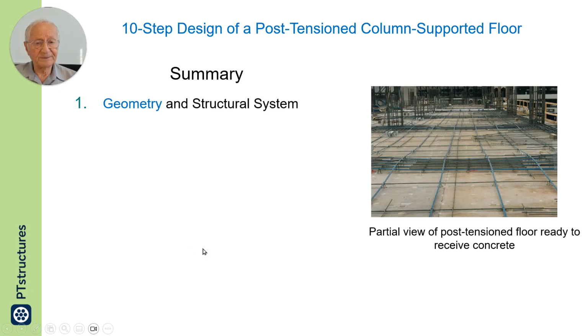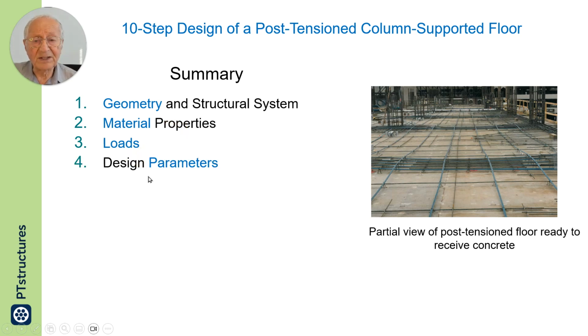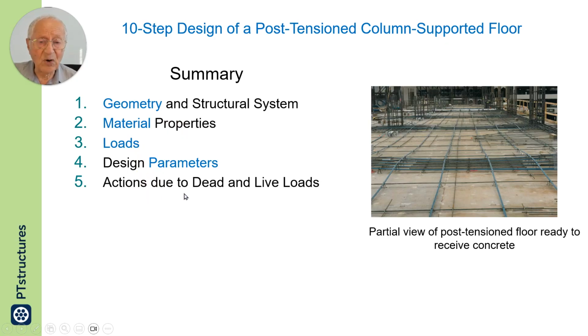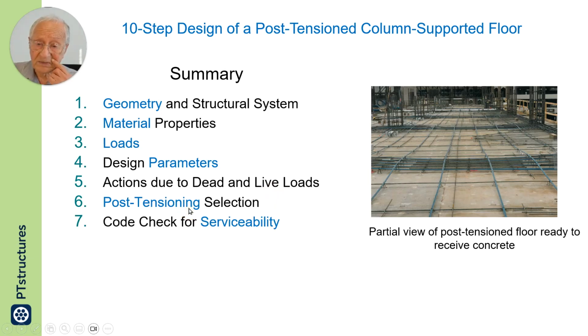So in summary, I defined the geometry, that was step number 1, defined material properties, defined loads, defined design parameters, then calculated the moments due to dead and live loads. We selected post-tensioning using two assumptions, pre-compression and uplift, to enable us to come up with the initial post-tensioning.